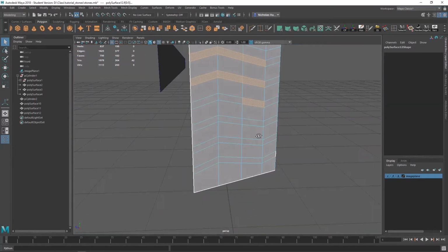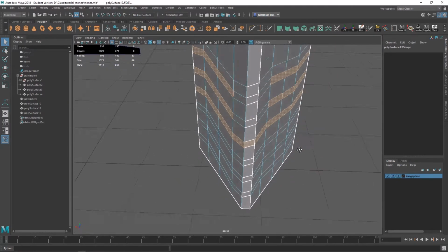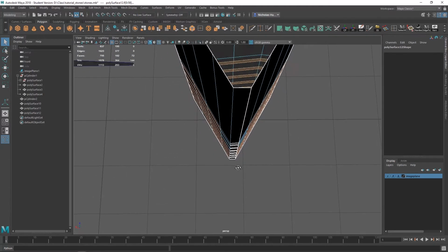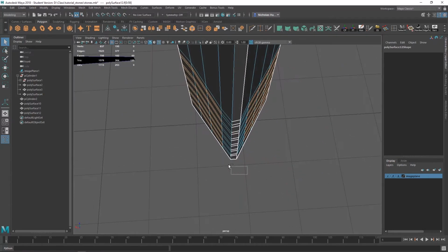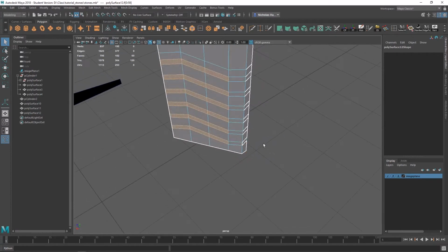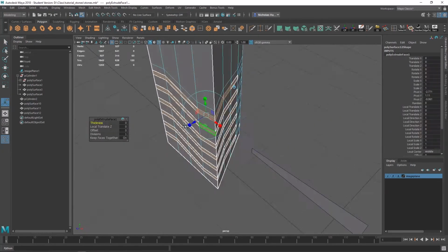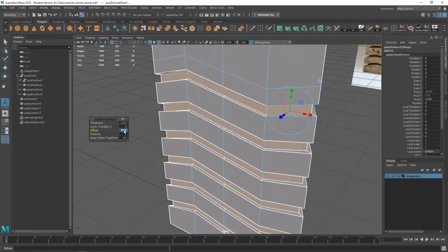And we might be able to get away with it a little bit quicker by doing it this way. Still double clicking. Nope. I can actually show you this too. This might be faster. So Shift, double click, select the whole loop. Then top down, you can just marquee select right there. And that'll deselect everything. So remember, it's Control marquee select, not Shift or Shift Control marquee select. So now we've got those pieces. Now we will extrude inwards. I think our thickness was 0.03, minus 0.03. And then the offset was 0.005.